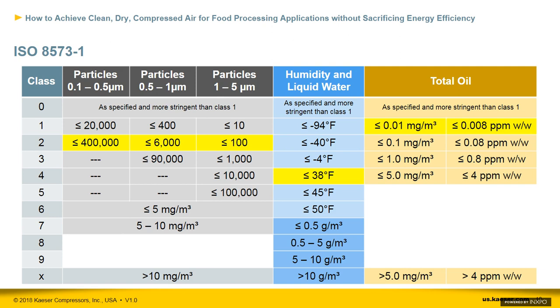All right, so here's a set of specifications for compressed air quality: ISO 8573-1. This sets classes for specific levels of particulates, water, and oil. Specifying the ISO class level for each contaminant can provide usable guidelines for selecting compressed air dryers and filters. You take a specific level from each of the 3 categories to give the ISO class. So, for example, ISO class 2.4.1 would be class 2 for particulates, class 4 for water, and class 1 for oil, and then you select dryers and filters to meet those specs.